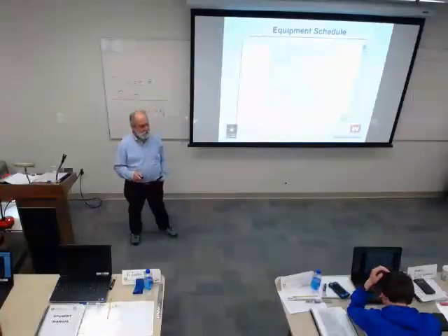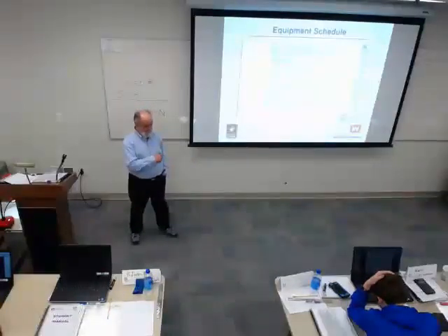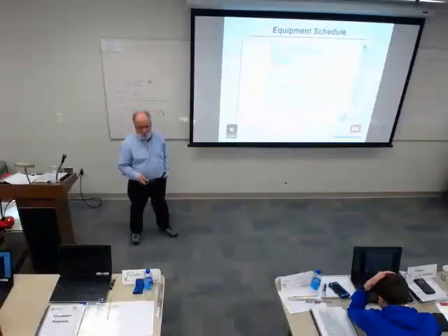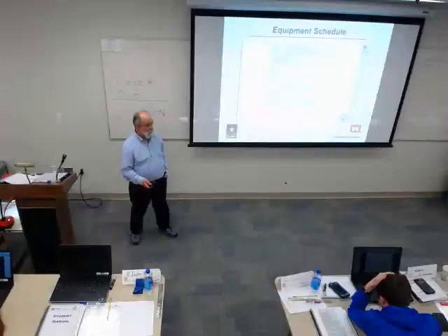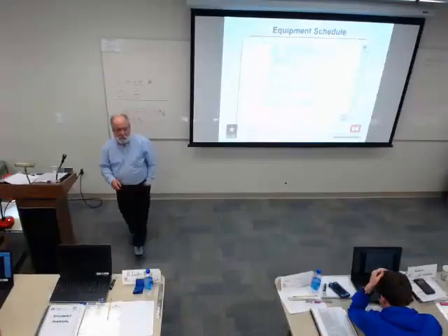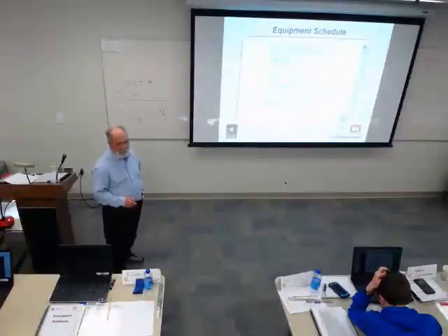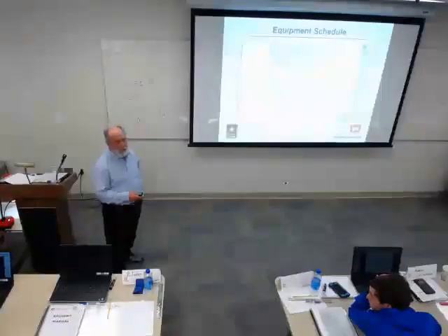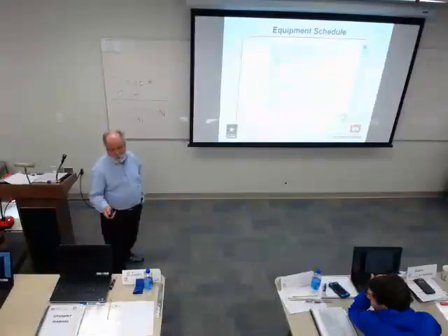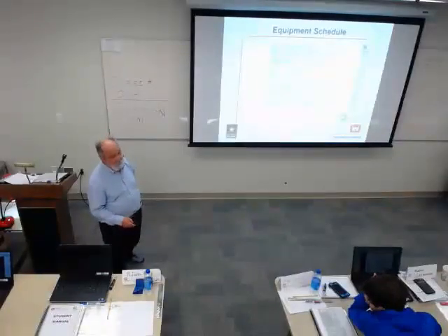If the engineer asks for a specific class, that will be on here too. Otherwise, the vendor will choose the class, unless it's addressed in the spec. So if it's not in the spec or on here, you're almost stuck arguing with the vendor about the class of the wheel, if you have a strong suspicion that on this job you're going to have to increase fan speed.